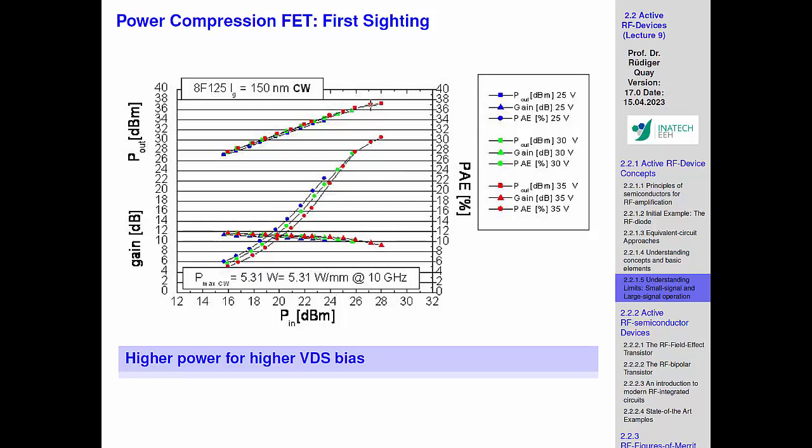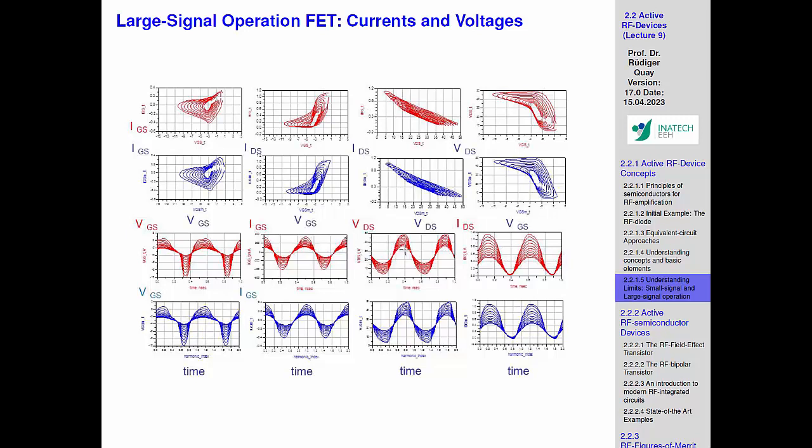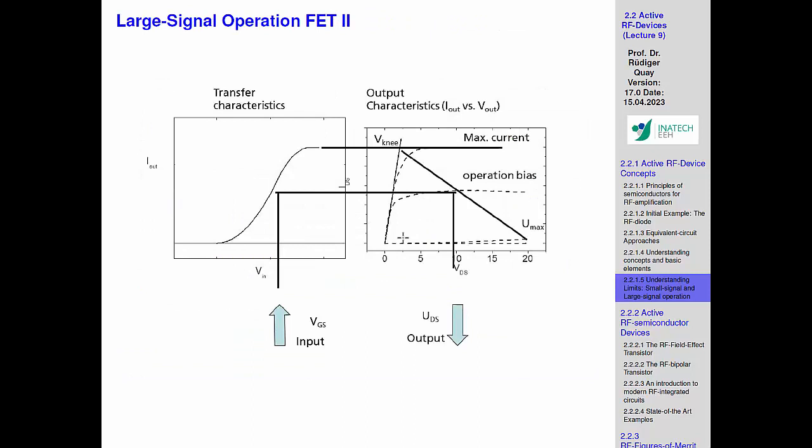And you see that this is the low input power case. This is a perfect sine wave. And you see for high power, it really starts to create some uneven shapes, which is just a representation of compression. And the other thing why I'm putting this up is, in this representation, if we just draw the current, we don't see any RF, because it's lost. This is, in principle, what we see here.